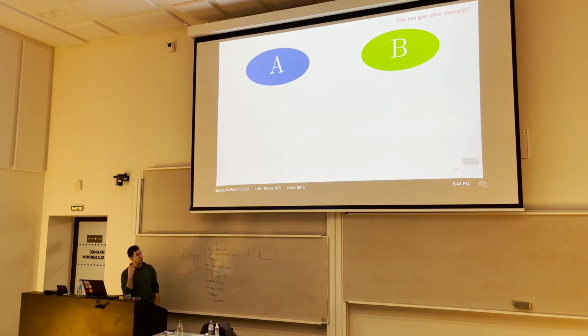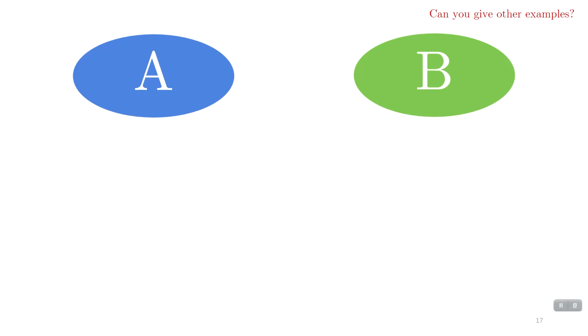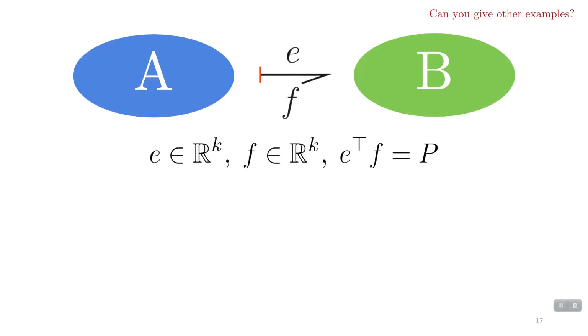So we can describe interaction of those two systems A and B by a power flow. This half arrow describes the direction of power. So here, power goes from A to B. And in order to get power, we need two variables, something which is called an effort, E, and something which is called flow, F. Effort is something like force, and flow is something like velocity.